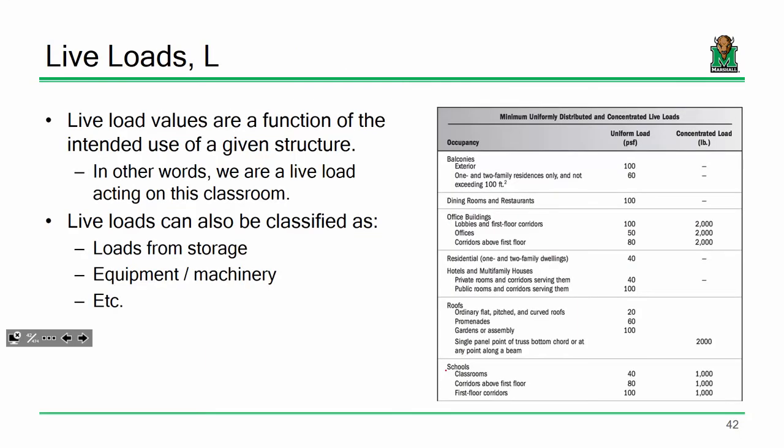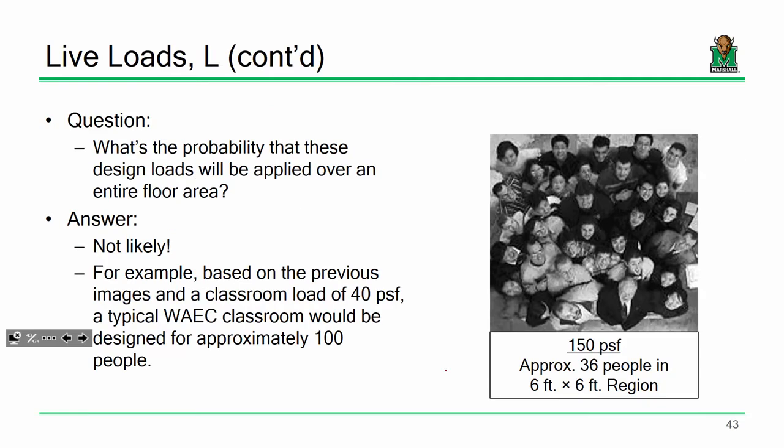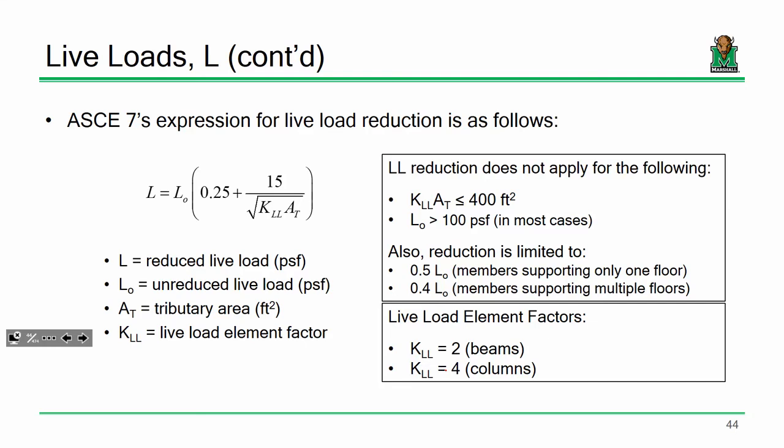We're going to talk about this in concrete design next time, but live loads also are dependent on the type of structure you're assessing, whether or not you're looking at a library or a school or an office building. You have different live loads, but I know my concrete folks also remember live load reduction, right? So I'll soft pedal that for now because we're going to talk about that in very significant detail later. But the question is, do you have to design for the entire maximum live load in most cases? And the answer is no. And that's where live load reduction comes into play. And I know my concrete folks remember that.